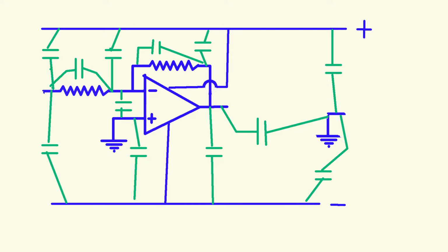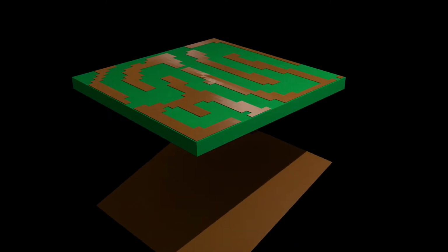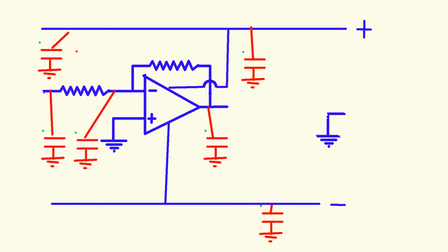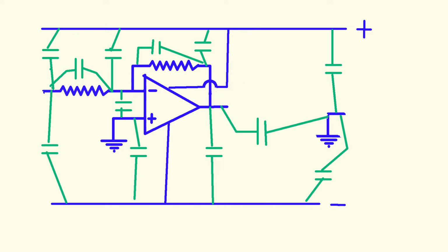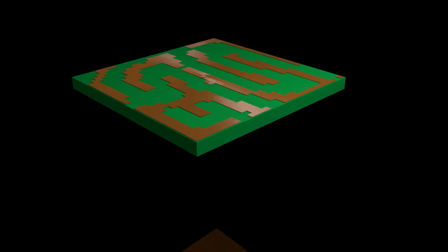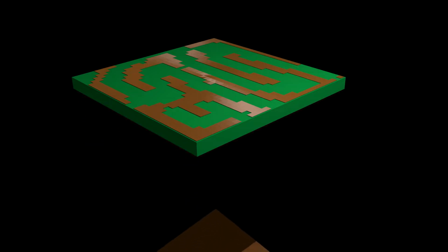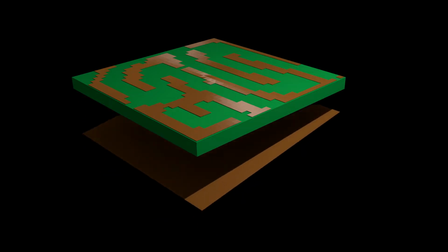To minimize the effect, most designers cover one side of a circuit board with a continuous sheet of metal connected to ground, called a ground plane. With a ground plane, a conductor's grounded capacitance is greater than any capacitance between conductors, grounding unwanted signals. Putting a ground plane on your circuit board is the easiest way to eliminate potential problems.